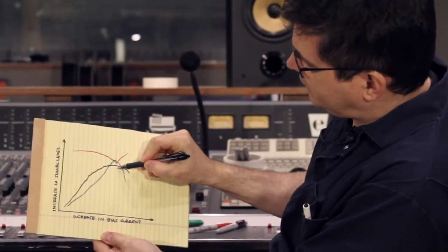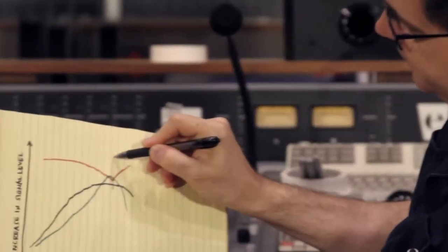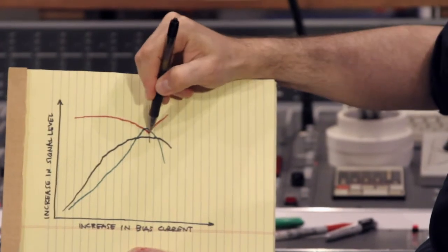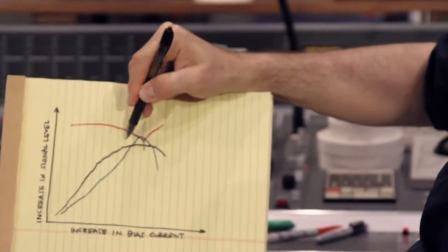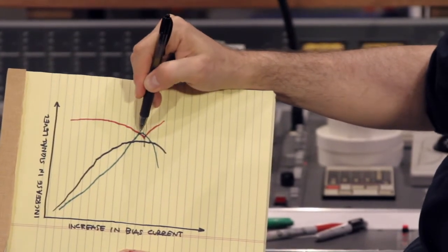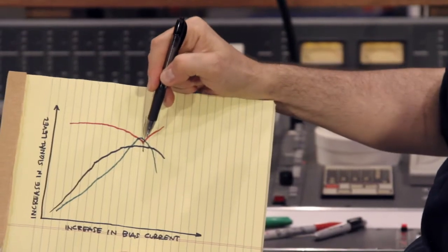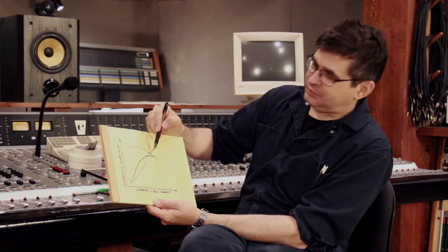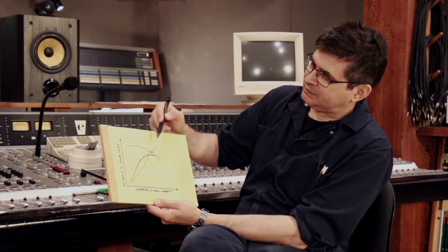Actually, I've indicated that poorly. But that point right there is what we're describing. Where the noise and distortion components are at a minimum, you're still on the plateau of general sensitivity, and the high frequency response is still reasonably good. That point, the point of lowest noise and distortion, will always be past the point of peak sensitivity of high frequency response.